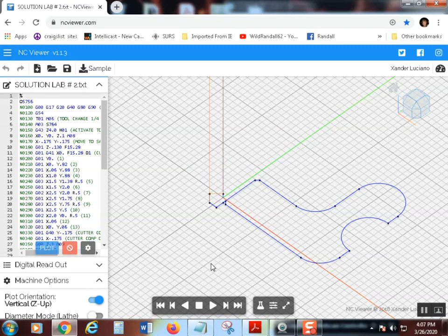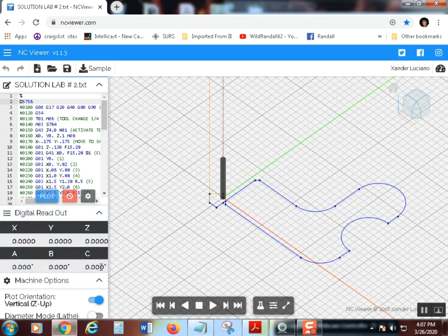I don't see why. So let's go ahead and rewind it, okay? And we'll step it forward one at a time. Here we go. We're at X0, Y0, Z.1. Let's put our digital readout on. Okay, let's see if that works. Okay, once we get to a move here. Okay, Z came down to 4 inches, just like it was supposed to. Activated my tool length offset. Now it's at X0, Y0, and Z's at 100 thousandths. Hard to see it, but it did show it right here. So there we go. Okay, next move, we should go to our safe start spot for our cutter comp.